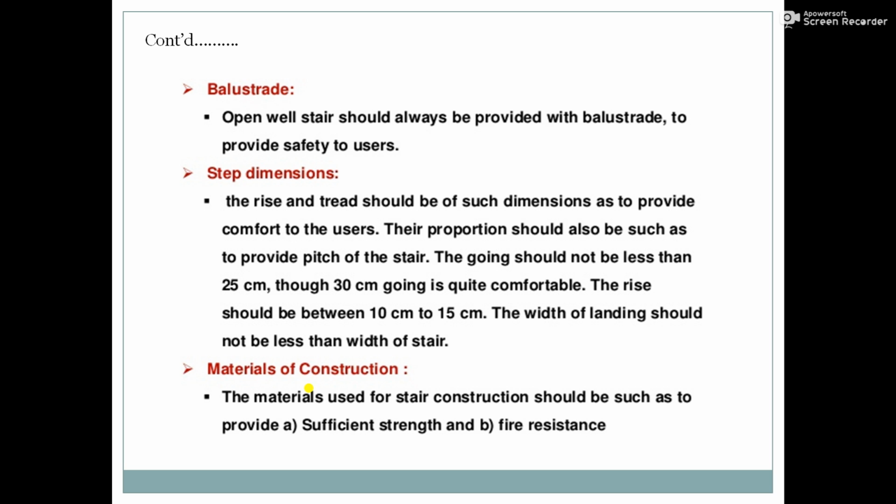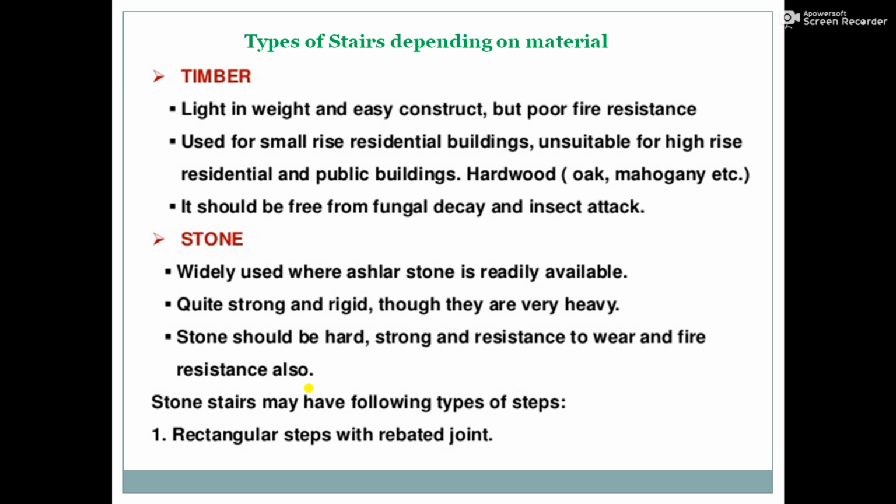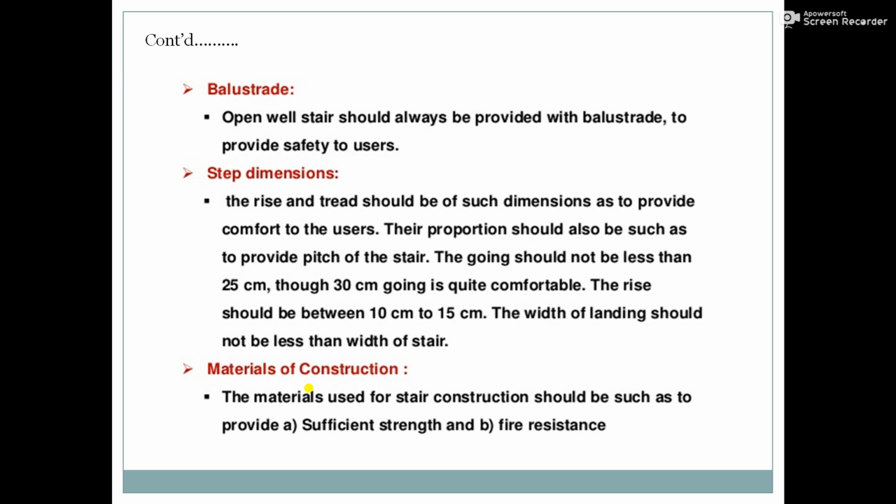Then the step dimensions. The rise and the tread should be of such dimensions as to provide comfort to the users. Their proportion should also be such as to provide a proper pitch of the stairs. The going should not be less than 25 centimeters; up to 30 centimeters going is quite comfortable. The rise should be between 10 centimeters and 15 centimeters. The width of the landing should not be less than the width of the staircase. So these are some important points which are considered for ease of use of the staircase.